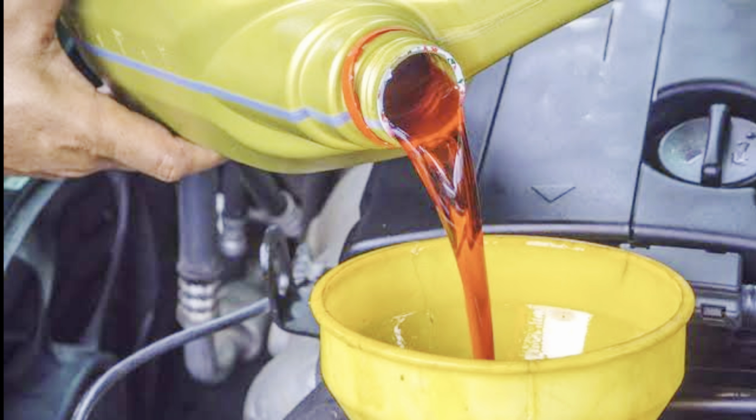In order to keep the transmission at normal operating temperature, a portion of the fluid is sent through one of 2 steel tubes to a special chamber that is submerged in antifreeze in the radiator. Fluid passing through this chamber is cooled and then returned to the transmission through the other steel tube. A typical transmission has an average of 10 quarts of fluid between the transmission, torque converter, and cooler tank.